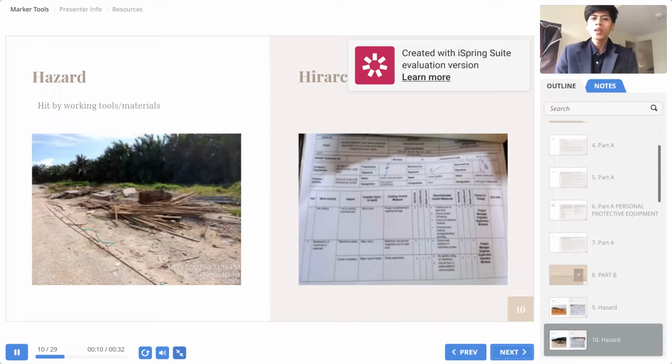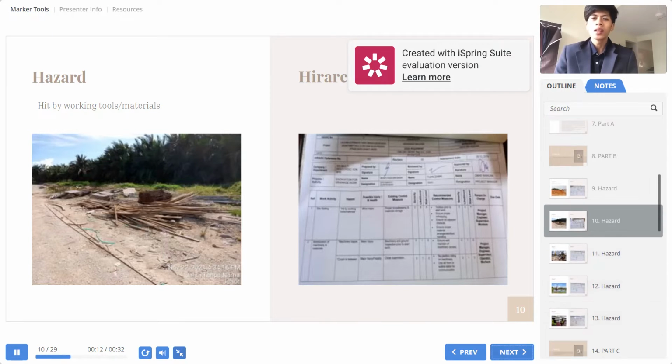The possible injury caused by the hazard is minor injury. The risk assessment for this case is 2 for severity, 4 for the likelihood, making the risk level at 8, which is considered as medium at the site. For risk control, the recommended control measures are such as toolbox meeting before start work, ensure proper housekeeping, no adjacent obstacle, and proper material arrangement, which should be taken note by the person in charge.